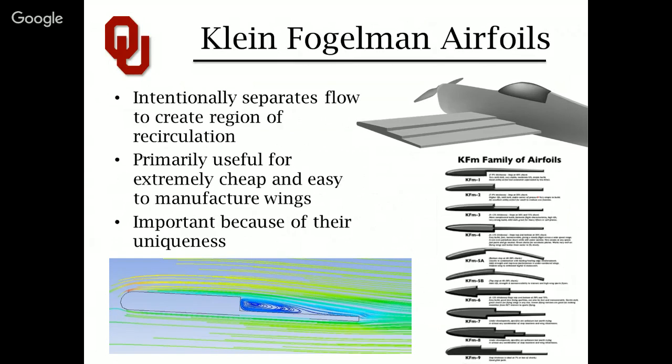Primarily, these are made for easy construction. Quite honestly, they came about because somebody wanted to make a foam RC airplane, and they wanted to make a very easy, simple wing. So if they crashed, or if they got in a dogfight with a friend, if they collided with a tree, whatever, they could make a new wing really, really fast by just bending foam board around itself in various ways. So that's why you see all these stepped construction methods.